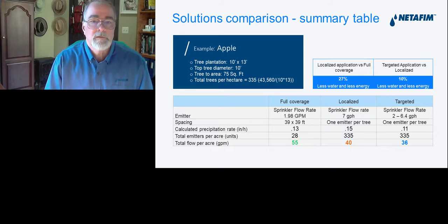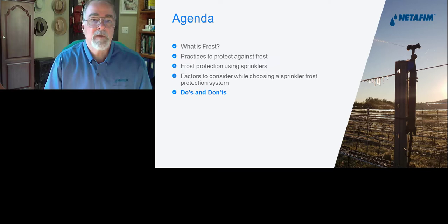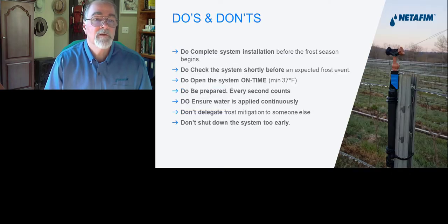So the do's and the don'ts. Some of these we've already covered, but they're important to reiterate. And we're going to touch on those again briefly and then move on. So, of course, we want to have the system installed before the frost season. Kind of makes sense, right? We want to make sure it operates properly. We want to run that system. I usually start a few days before. We want to make sure every single emission device is working at its full flow rate. We want to make sure that the pumps' oil is changed, the fuel tanks are full, whatever may occur there, and make sure that all the valves work, everything's ready to go.